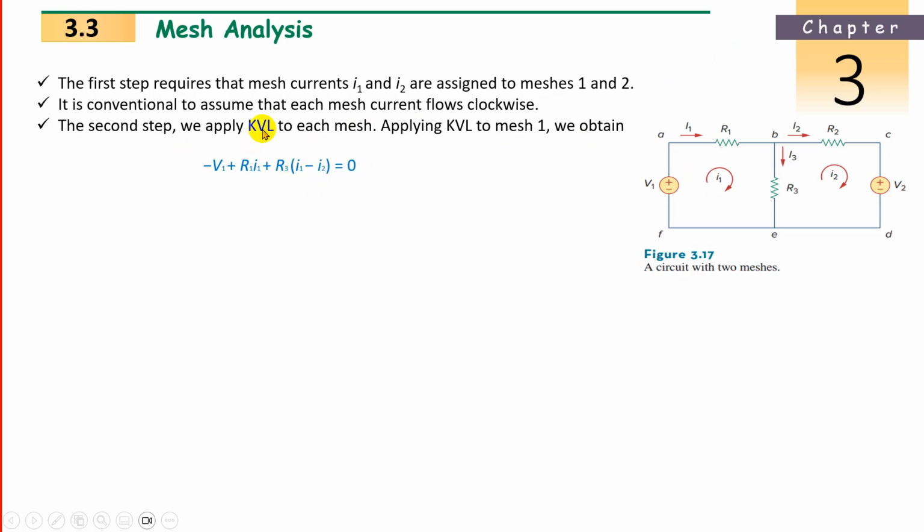This is the first loop equation. Now, as in nodal analysis, always arrange the equation with the variables on one side equal to constants. Here also, what are the variables? Small I1, I2 are the variables. What are the constants? The voltage source. V is a constant. Take it to the other side. Solve the equation such that I1 plus I2 or I1 minus I2 equals something like that.